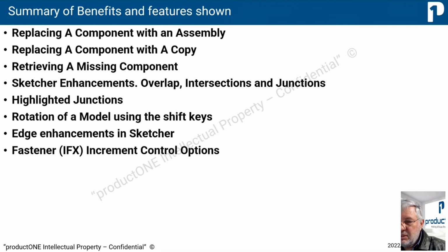You can now set the incremental size for the depth and diameter spin buttons in the screw and dowel dialog boxes. Different increment sizes can be set for the depth and diameter, and also for the millimeter and inch units. Using interface locations, click Intelligent Tool Fasteners options. What's the benefit of this enhancement? This enhancement allows you to adjust the incremental size based on your requirements. Previously, you could increase or decrease the spin control values only at the default incremental sizes. The new option enables you to customize the increase sizes for spin buttons in the screw and dowel dialog boxes.